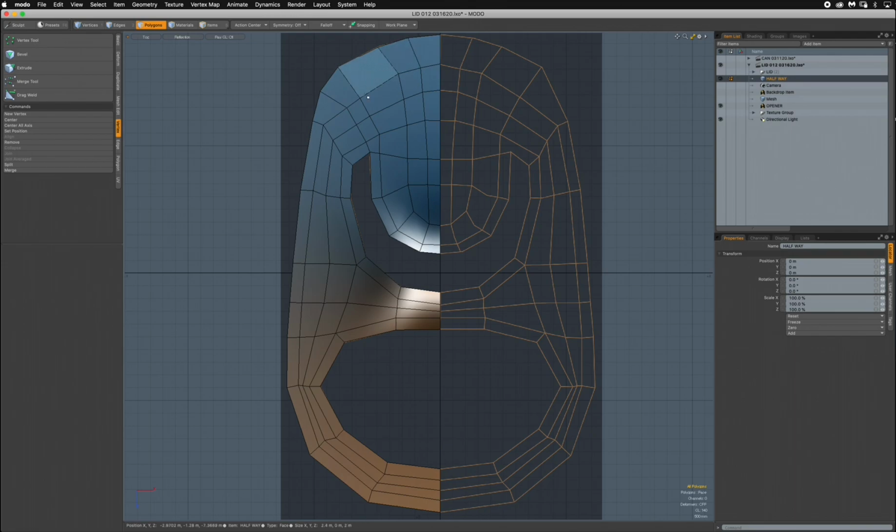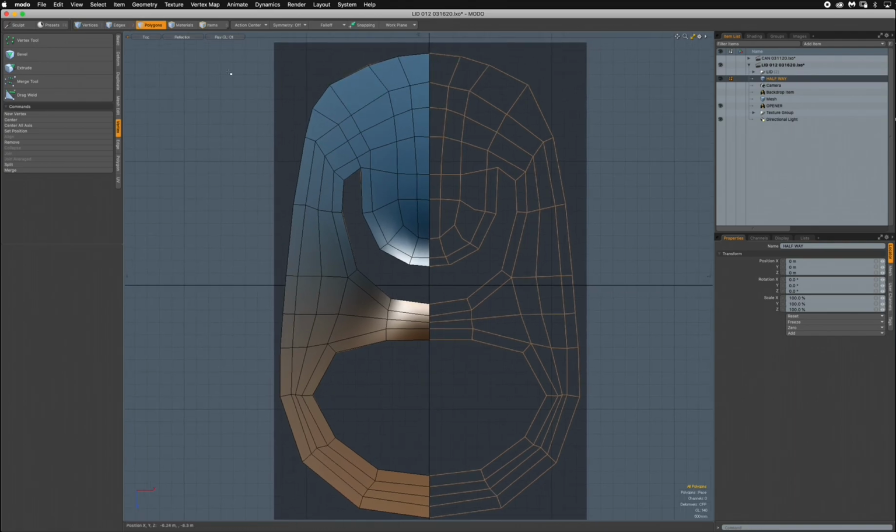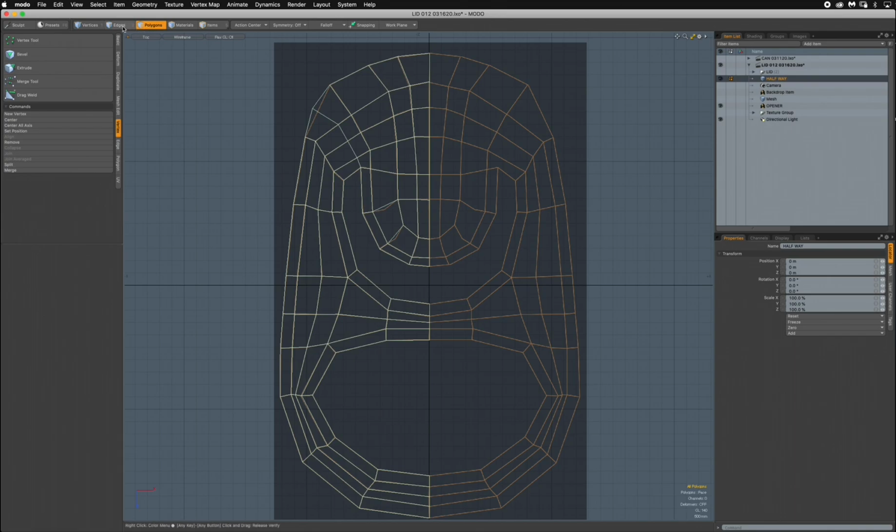Now once you're at the halfway point, make sure you select all these edges and that they're 100% straight like we talked about. If you don't know, you just get these edges of vertices and do a loop slice with your mouse around the edge. Shift, select them all, scale them and make sure they are at the red 0 on the axis here.